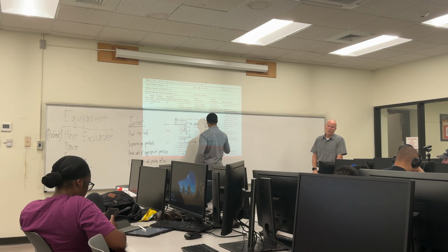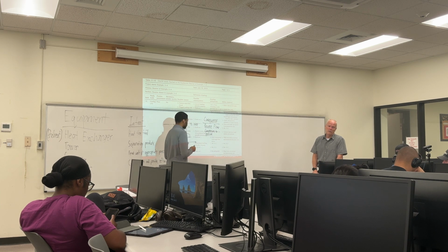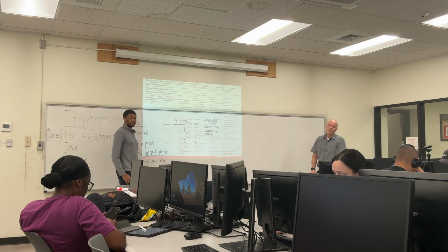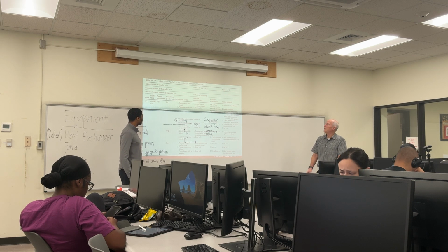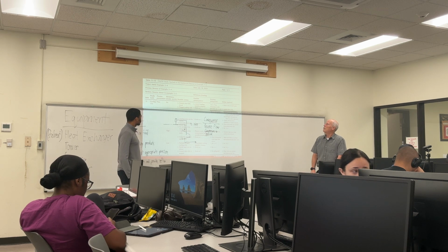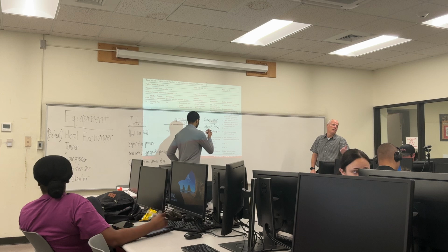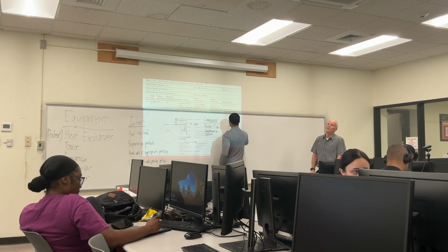Now, we can go into existing safeguards, possible causes, or action required. Which would you like? The scenarios are the possible causes. We need to get there eventually. We need to have scenarios for why this would happen. But what about existing safeguards? What stops it? So existing safeguards, yeah, was a check valve.